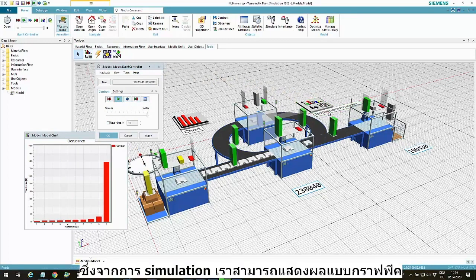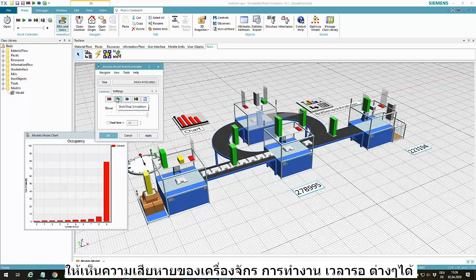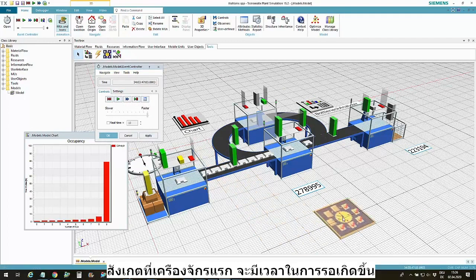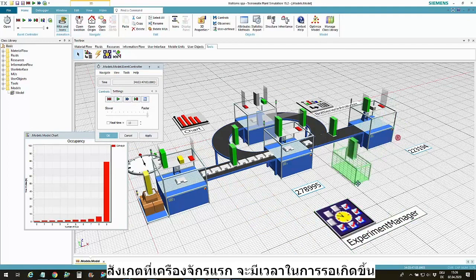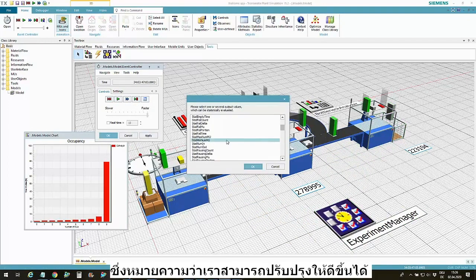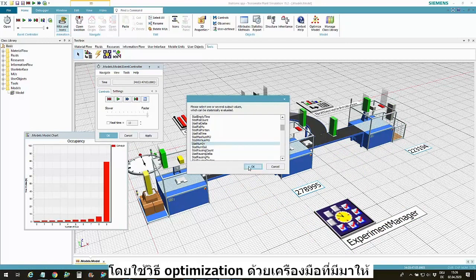For the analysis of the model, there's a graphical tool, the bottleneck analyzer, and it shows the statistics. It shows in green the utilization, yellow blocking times, and red the failures. And we see that the failures are used in all the stations. And in the first machine, we have a backlog, so we have a blocking, and that means that there is a potential for optimization in this model.